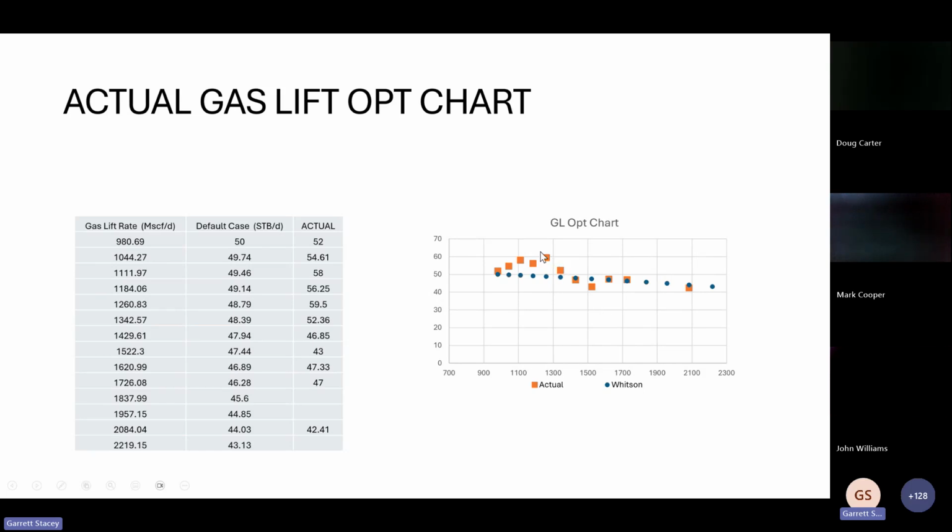And that's where when you see we're kind of getting this spike at 1,300 or so. And sometimes what you have to watch out for is, if you do that, you will sometimes have a low data set type thing where you have one day as you're lowering it where it hits that number, and so you get an artificially high number rather than sustained production there. But again, this chart of theoretical versus actual is exceptionally helpful when doing postmortems on the gas lift changes.